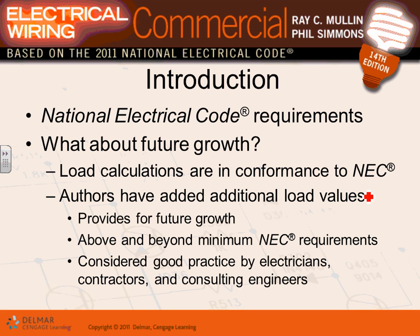All the calculation, guys, is based on the NEC code book. Future growth. I will remind you guys, in our project, we had a 5,000 square foot future growth, right? We added this one. We also have a future condenser. You guys remember that? So you have to always accommodate for future growth. If you don't have the equipment to accommodate for this one, it's a good idea to put 10 to 15% over on your system for future growth.